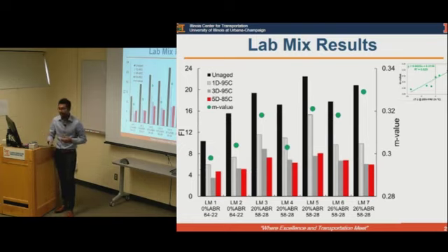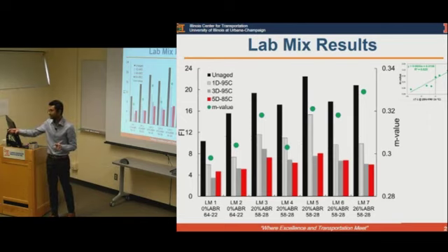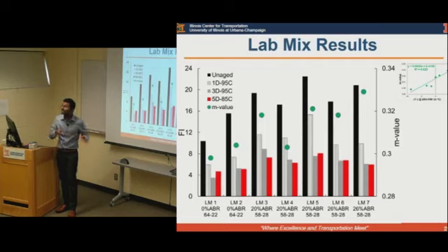So if you have a mixture, for example, with a binder modification with something like a cooked oil, because oil is kind of a hydrocarbon, you can add that. So in the long term, the change in that chemistry for different binders can differ, because chemically they're different. There's no one unique chemical structure for asphalt binder. So that variability will eventually affect the rheological performance of the binder, and that affects the performance. So here with IFID, we're trying to measure the performance, but at the same time we need to validate whether this chemistry plays that role, and how we can incorporate it. If we understand the chemistry, can we improve the performance? It's like supporting your performance. The test, the protocol will tell you whether it performs or not, but at the same time we need to understand the fundamentals behind these changes, and whether we can somehow engineer that.